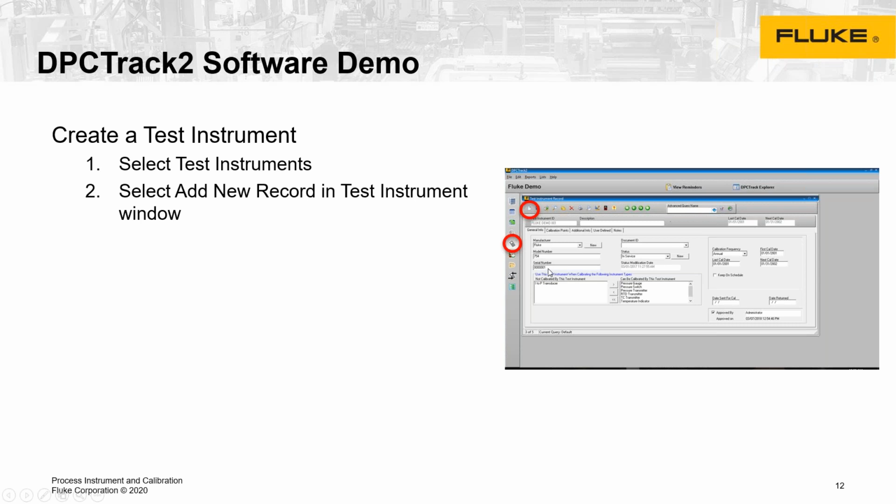The manufacturer and serial number would be some of the most important information, as that is how the software will bond the calibration record back to the device that has been calibrated. You have the ability, if you have an annual certification, to actually import the document. So in this case, if Fluke 754 is being created as the test instrument, we can take the annual certification of that 754 and import that document into the software. So we have further reverse traceability of where that calibrator was calibrated.